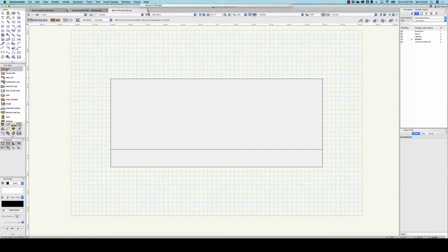So we're going to use the wall tool in its first mode, the left control mode, and we're going to start drawing here at our 2 foot mark that we've just established, and we're going to go up to the corner, and then we're going to start pulling over. I'm going to tab, and this wall is 18 feet 6, return, and now I'm going to pull down, and here we want to go 3 feet, so tab 36, return.